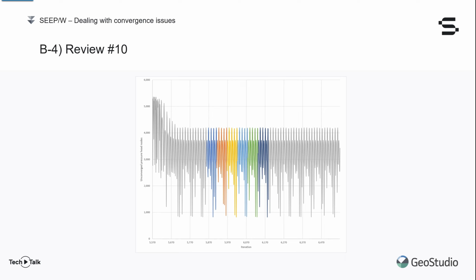This indicates the solver is stuck in a repeated substitution loop which won't provide any better results even with a large number of iterations being allowed. High nonlinearity in the hydraulic conductivity functions used for the various materials in the domain is causing this convergence issue. The solver should be allowed to try out smaller solution change increments to account for the large nonlinearity of the material models. This is where altering the under-relaxation criteria can do wonders.